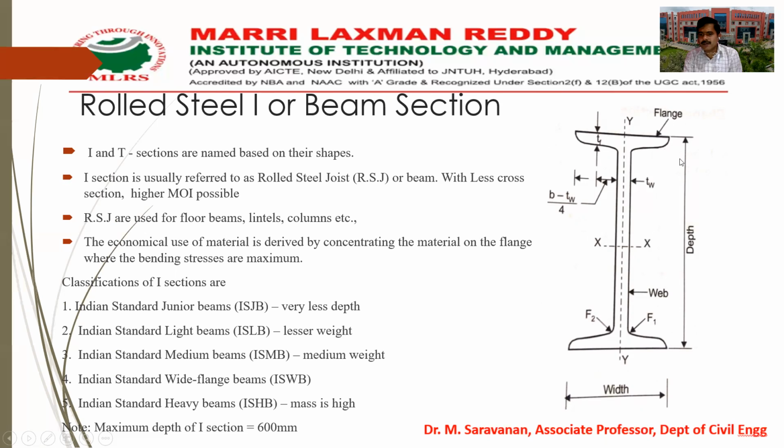So Y is nothing but this D by 2. So when the depth is increased, the bending stress will be increased.